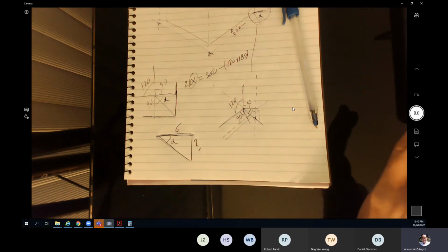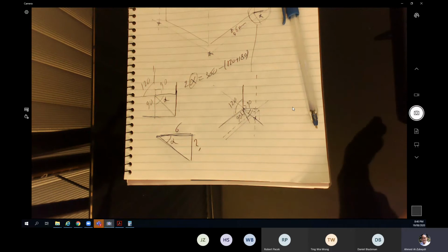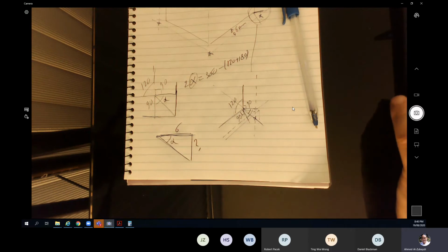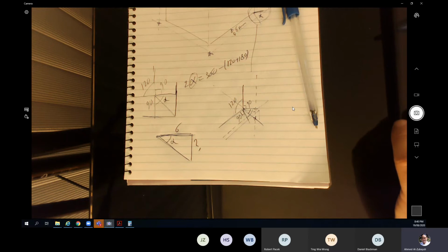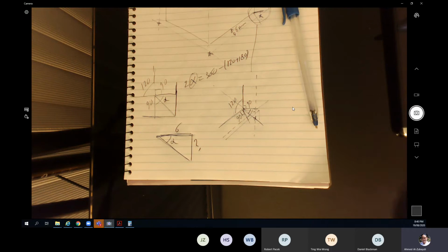In the route sheet, we mention the operation number, what the operation is, details of the operation, and what machine we need to do it. And sometimes, we're going to talk about this in future lectures, we need to write down the expected time required to do the operation. Thus we will be able to calculate the total time required to make one part.